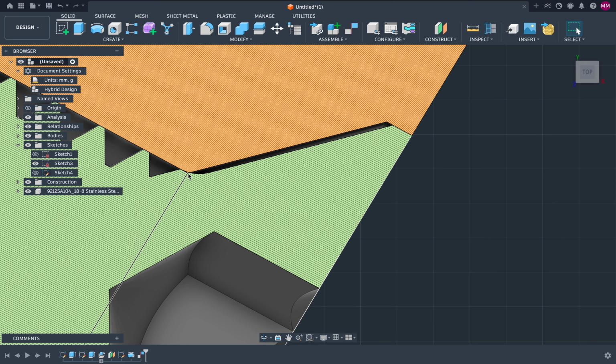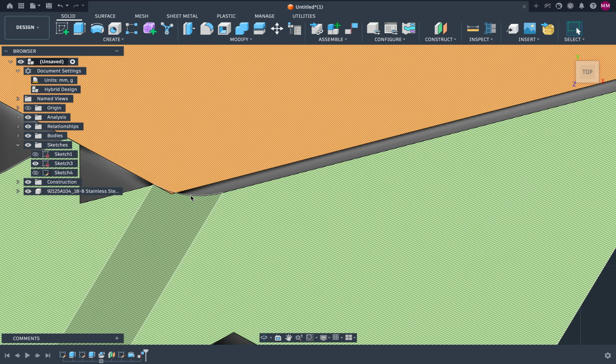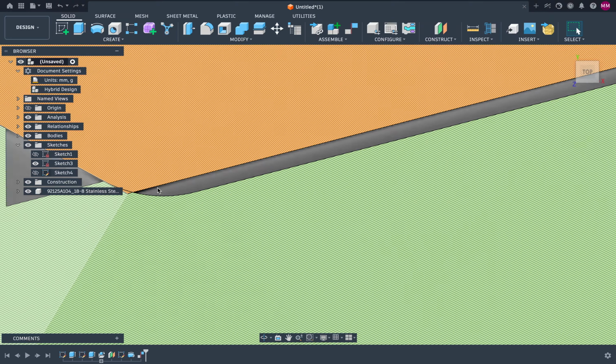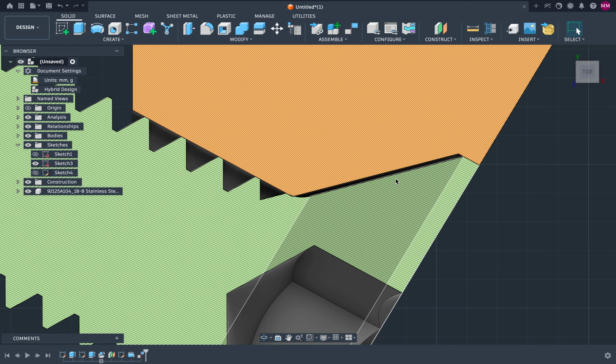There we have a tiny interference here, but in the case of 3D printing, it's probably better to have some, right? Because it is plastic and it can flex and be deformed, so it will probably lead only to a more snug fit. So this is actually good, and it will not be obstructed by any nonsense error with this flush face. Also, what we can do, we have seen that this one is flush, and again we just found out that 3D printers are not perfect.